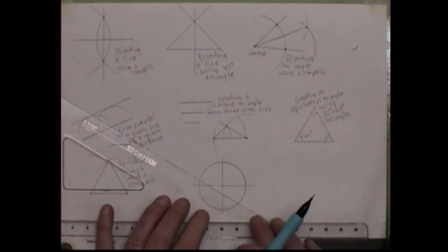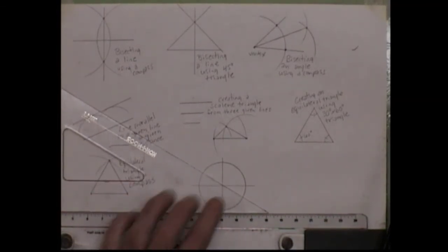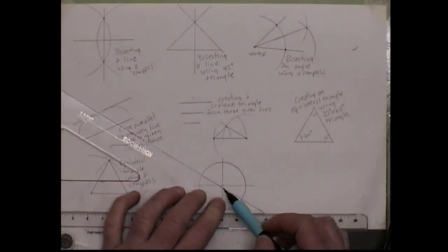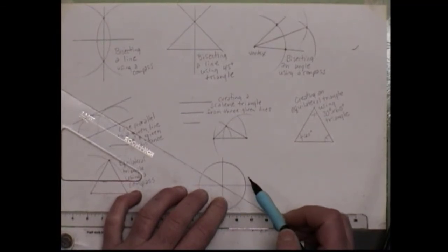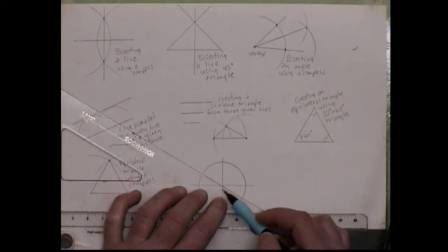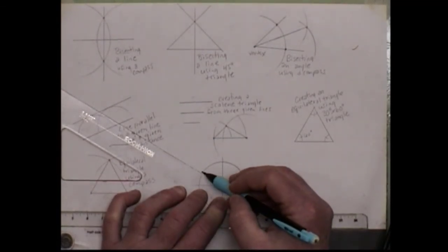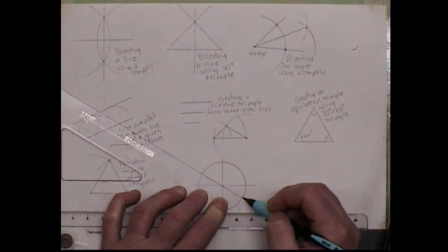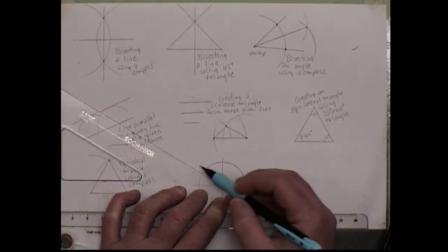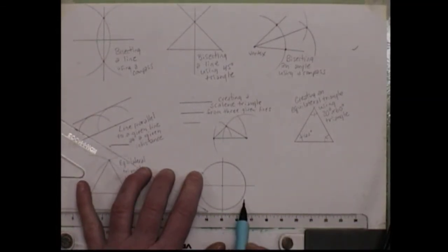At 30 degrees. So my 30-60 triangle is up against my horizontal straight edge, and I want to line it up with my center line. So I'm making it tangent to my center line, or my center point right there. I'm putting my 30-degree side tangent to my center point, and I'm just going to make a little notch, like a little measurement point, on each side. So in the end, I have a measurement point here and here.